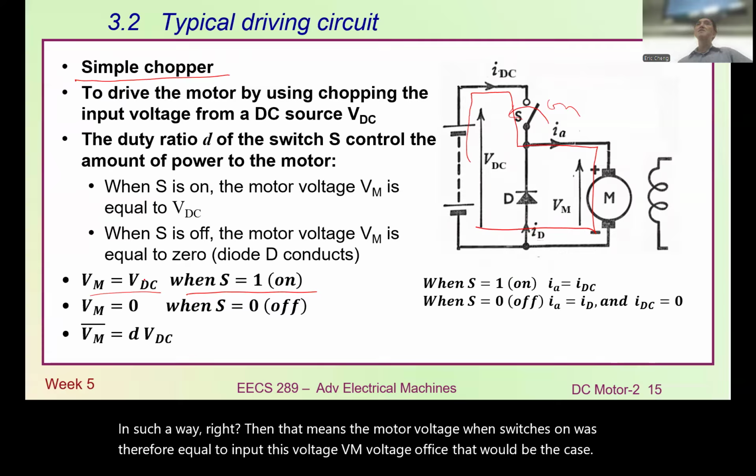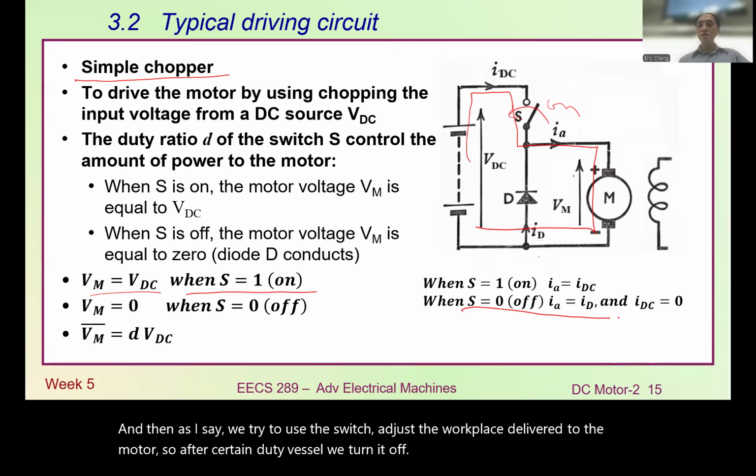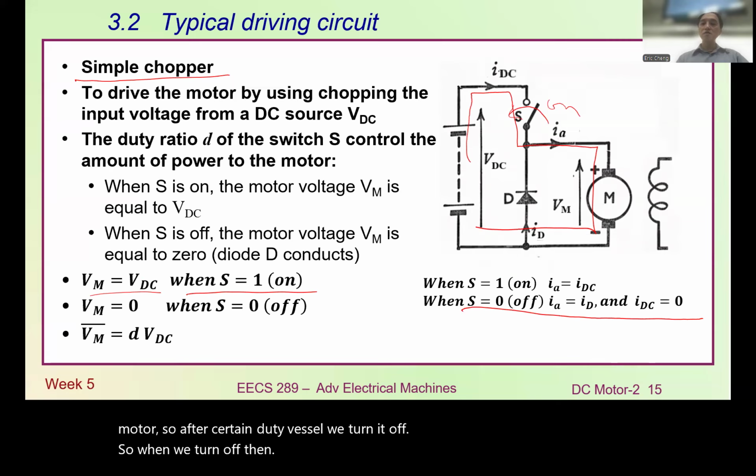And then, as I say, we try to use the switch to adjust the voltage delivered to the motor. So after a certain duty ratio, we turn it off.